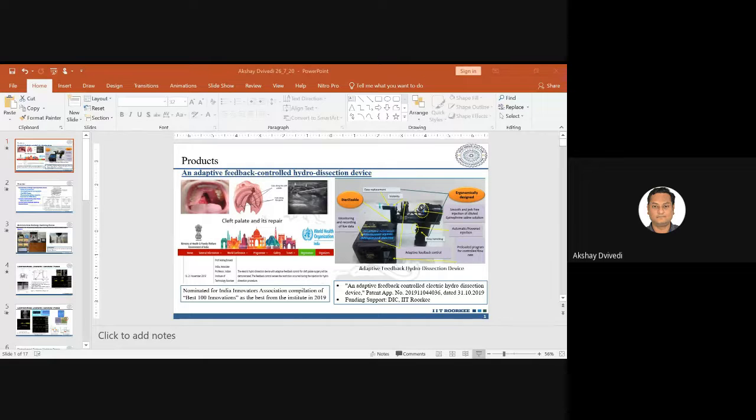Answer is yes. Are you spending too much money in development of such a texture tool? The answer for this is no. Here, this wire brush is a cheap thing, and working on an EDM has very little cost in terms of its operations. So more or less, the cost of fabricating this kind of texture tool is not too expensive. And the best part here is, if you can create this kind of texture, you can actually create a textured surface on the work material.